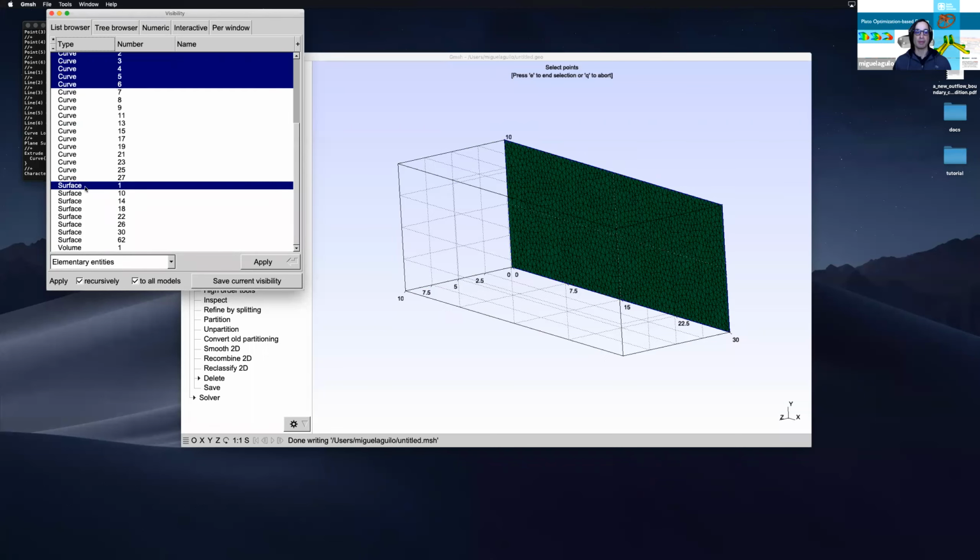But when Plato runs the translator that converts the mesh file into the Exodus file, he basically assigns names to these surfaces. And the names that are assigned are very simple. It's basically surface underscore and a number. And that number goes from 0 to the number of surfaces that you have in your geometry.